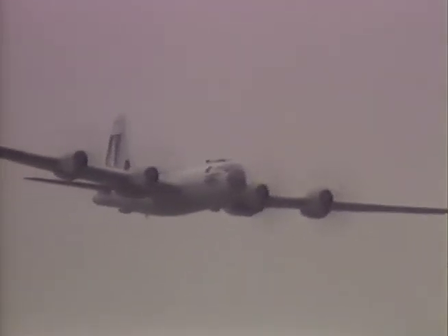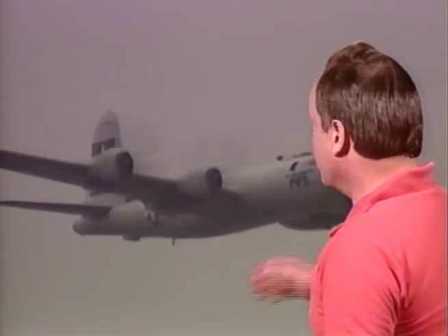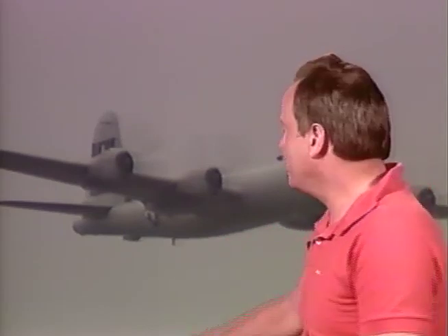Now, let you and I talk about superchargers and turbochargers. And boy, here's a beautiful example of an airplane that has supercharged engines, a B-29. It's a beautiful airplane. All right, they ask you a few questions about superchargers and turbochargers on the test. Let's talk about how they work. And the idea of both of these, by the way, is to compress the air going into the engine so you have higher manifold pressure than you would if you didn't have them.